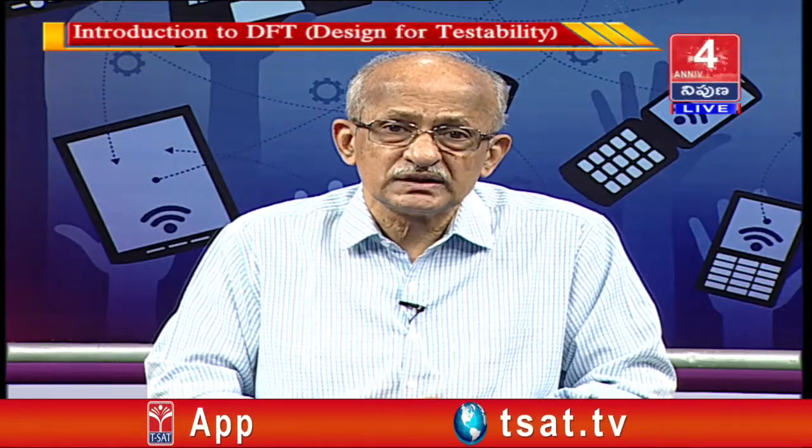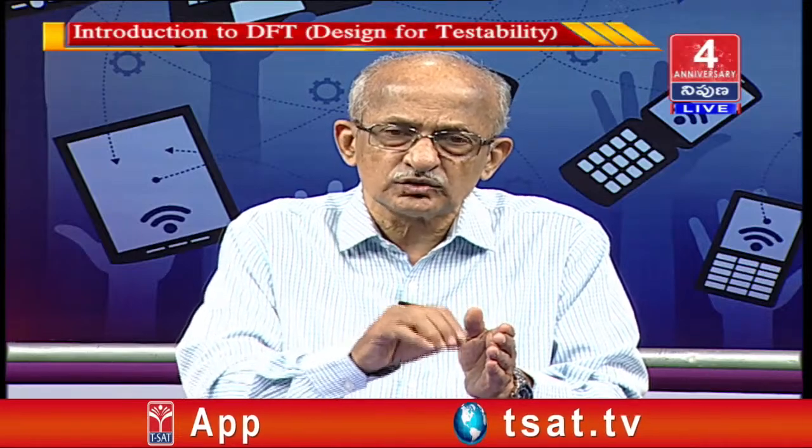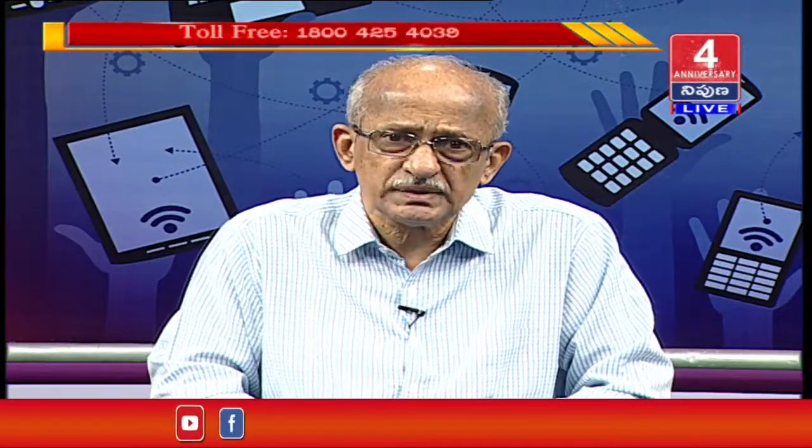When there is a delay defect in a chip, this chip cannot be made to work at 500 megahertz. It may work only at 250 megahertz. A processor designated to work at 500 megahertz may not do so because of a delay defect. However, it is not thrown away because it is not entirely junk. It is put in a different bin. This is what is called binning, and it is marked as working at 250 megahertz and sold at a lower price. It cannot be completely junked.